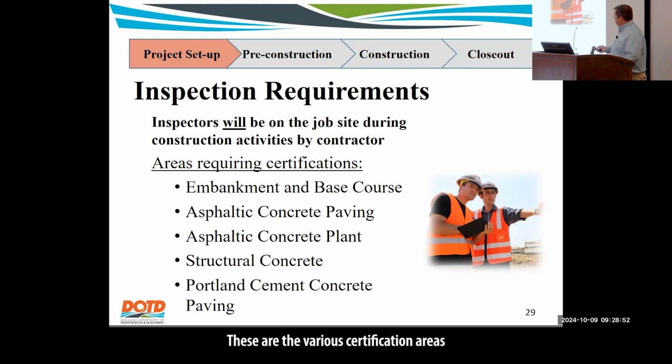These are the various certification areas that we have within the department. So if they are doing embankment and base course, and we're of course needing to run density tests on that, your inspector needs to be certified in embankment base course to run that density machine. That's not to say that you can't have qualified inspectors. Qualified inspectors and certified inspectors are two different things.